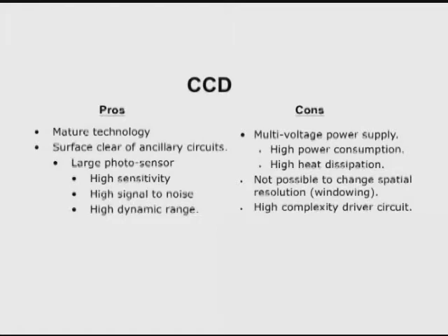It needs several different clocks to move the charges out of the vertical register into the horizontal register and so on. And what's typical on the CCD is that it has, when it aims into a very bright light, you will get what's called vertical smear, or this very vertical bright light. In the global shutter, which is typical of a CCD, when you use the shutter, you capture one complete image, not portions of it or lines.